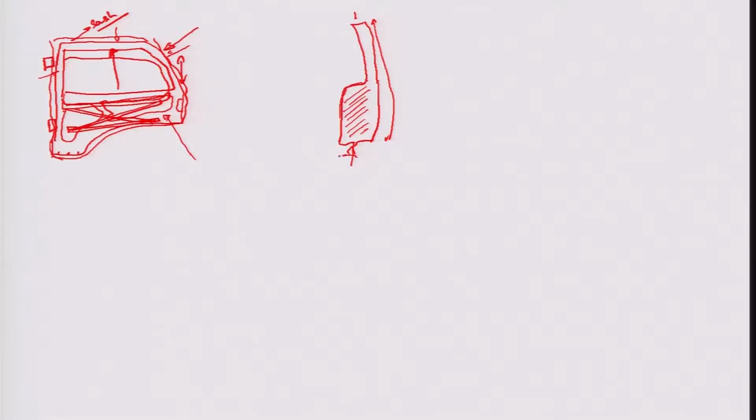The weather strip is connected in a manner so that the weather strip plays its role in terms of generation of pressure. There are certain lips which are probably there, which sit to the car body, okay, and if I look at it, the weather strip actually goes all the way round this periphery, as you can see here, and it might have more than two lips, and these are completely made up of rubber, with certain lips which would create a sort of pressure, a closing pressure of the door on the side body of the automotive, so that there is prevention of leakage which may happen.